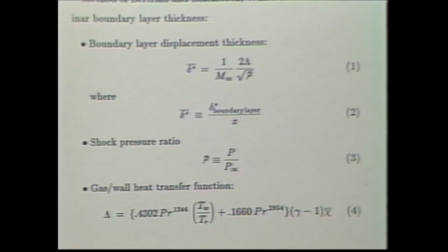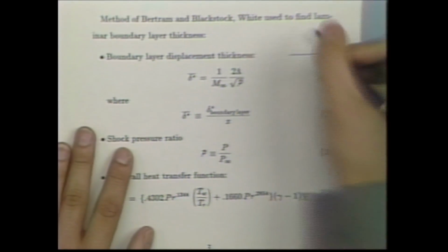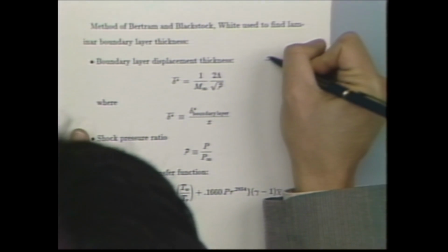What that suggests even more, and yesterday you heard a little bit about interaction theory, is that in hypersonic boundary layers, not only do we have thick boundary layers, but we have thick boundary layers which interact with the shock. Now, consider the front surface of a hypersonic inlet, the forebody of a NASP. The very, very front leading edge has a boundary layer, and that boundary layer has some slope because the boundary layer is growing. And let me reclaim a pen from someone. Thank you. If you picture that boundary layer, that'll be the flat surface. Let me make sure we can draw. And that boundary layer is growing along the surface.